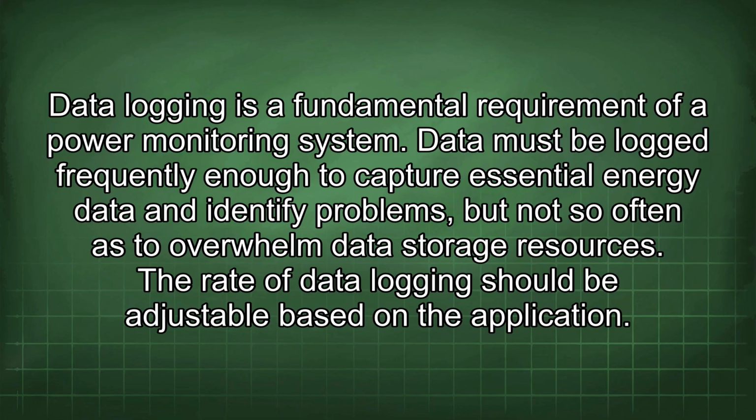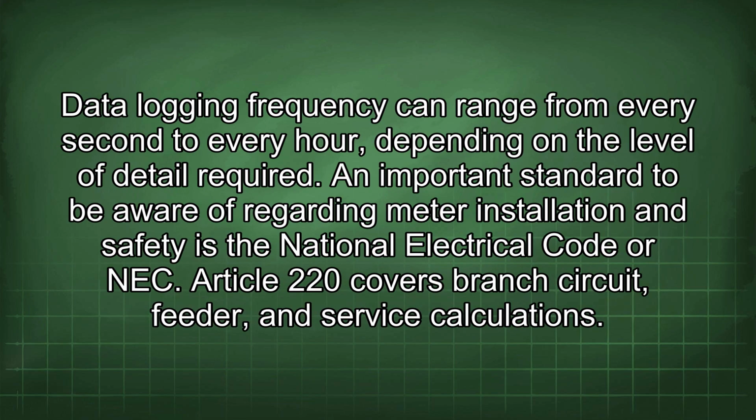Data logging is a fundamental requirement of a power monitoring system. Data must be logged frequently enough to capture essential energy data and identify problems, but not so often as to overwhelm data storage resources. The rate of data logging should be adjustable based on the application. Data logging frequency can range from every second to every hour, depending on the level of detail required.